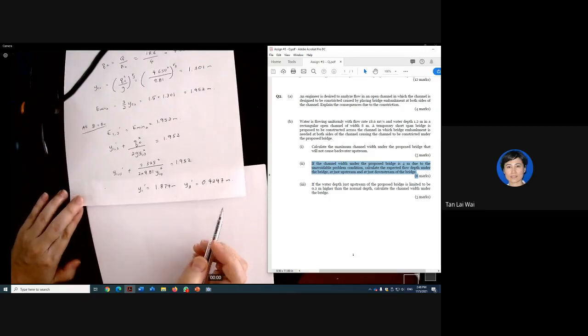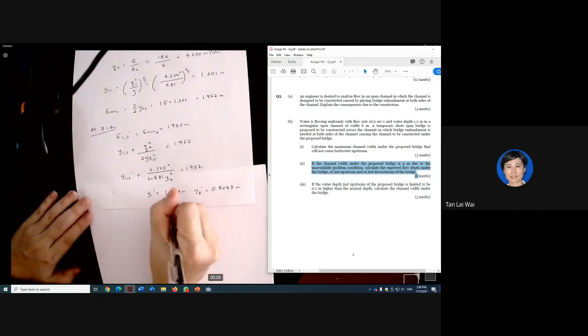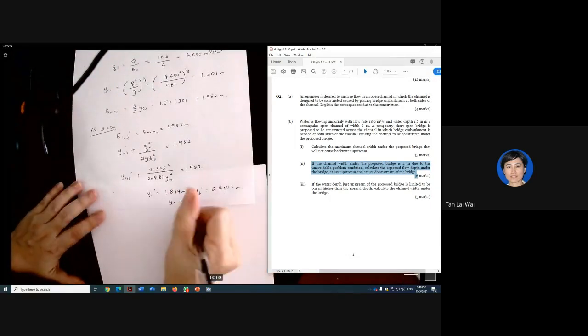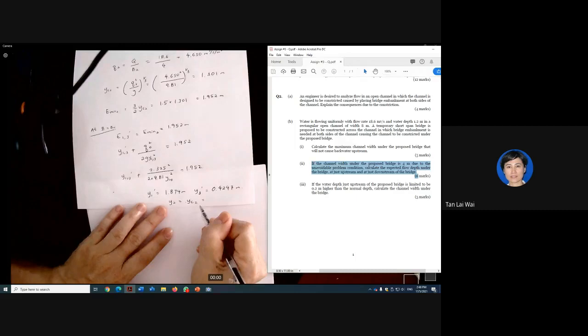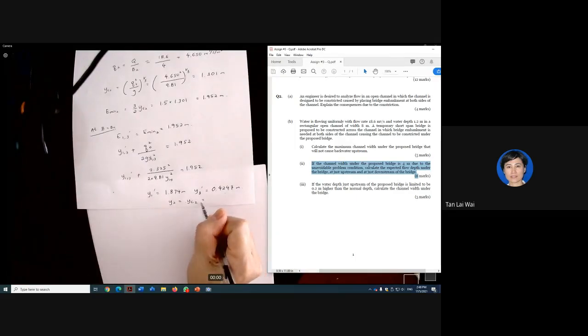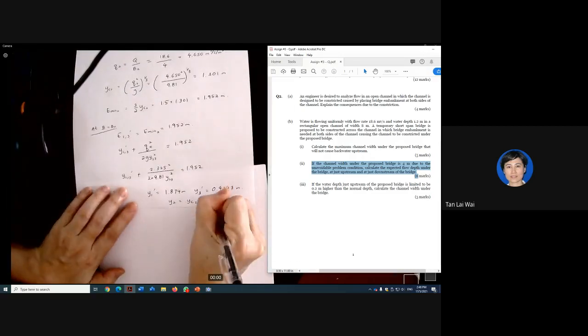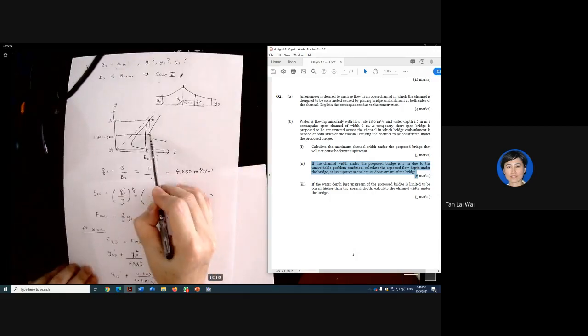Now, we have solved for y1, y3, and what is y2? Y2 is equal to what? Y2 should be yc2, right? Remember for case 2 and case 3, Y2 is in critical flow, therefore it should be equal to yc2, which is 1.310 meter, which falls on this curve here.